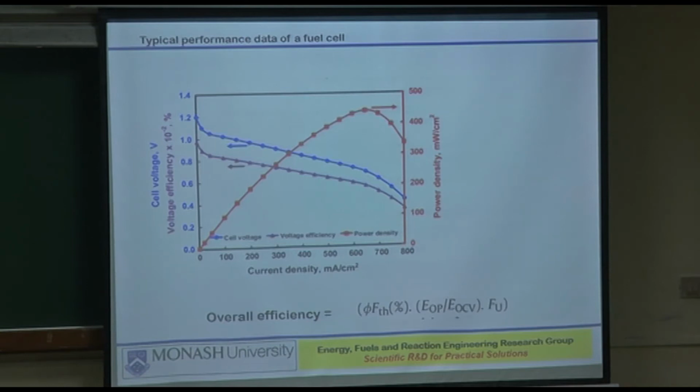Because, as you would expect, as happens in a gasifier or in a coal-fired furnace, the carbon burnout is never going to be 100%. The carbon conversion is not going to be 100%. You always have less than that, for lack of appropriate design or poor contact between the reactants and the solids. Here it is absolutely no exception.